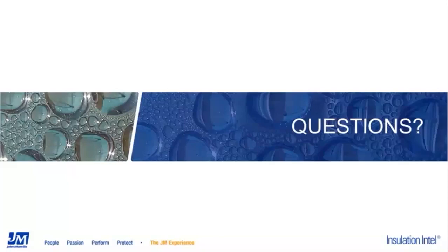Okay, but as Meredith said, just saying winery or brewing doesn't really tell you the whole story. I like to say that the insulation doesn't know what's inside the pipe. It only knows the pipe temperature and the climate around it. So it doesn't matter if it's wine, beer, or radioactive nerve gas inside. The insulation is designed based on the temperature of the pipe, the size of the pipe, the climate. So there's really not much difference between a brewery and a winery and refrigeration or chilled water. It just depends on which pipe temperatures you're talking about.